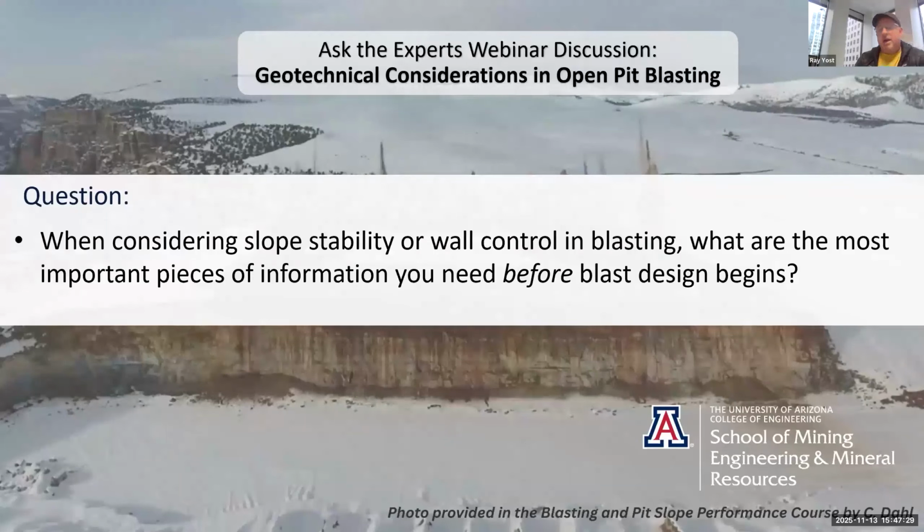So anything that the design is sensitive to, you really have to understand not only how close the blast is to it, but also where that blast energy is going relative to that structural orientation. So really, thinking about how you lay out that pattern relative to directing energy along that structure.